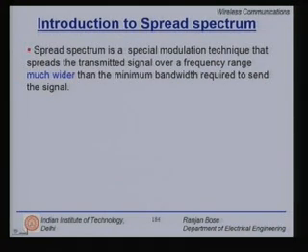For the first time, we are trying to be greedy in terms of bandwidth, but we know from Shannon's theorem that if we have to invest, it is better to invest in bandwidth than increasing your signal to noise ratio, because the capacity of a system grows linearly with bandwidth and logarithmically with SNR.